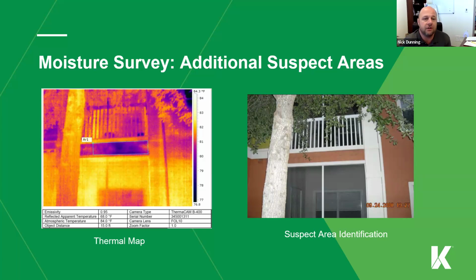If somebody shows up at 5 o'clock in the evening to do a thermal scan, it's not really going to help you that much. So you want to consider that. And just because someone has a lot of really nice thermal pictures, it does not necessarily mean that it's good information. So you want to understand when it was done and how they did it. If we haven't had rain recently and you haven't wet down the roof, there's no moisture really to be introduced there, so you're not really going to get a lot of good readings. So with thermal, it works well when done right. It has its limitations, but you want to make sure it's being done by somebody who has experience, or you're going to get a bunch of data that's not really all that helpful.